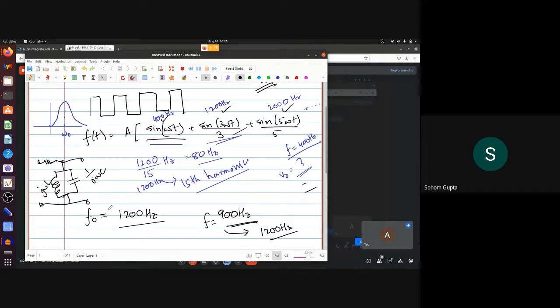But given a square wave coming in, what omega are we taking? That is the whole point. These expressions 1 by j omega c, j omega l, etc., all make sense only for a particular frequency sinusoid, not just a frequency. It only makes sense for sinusoidal inputs.